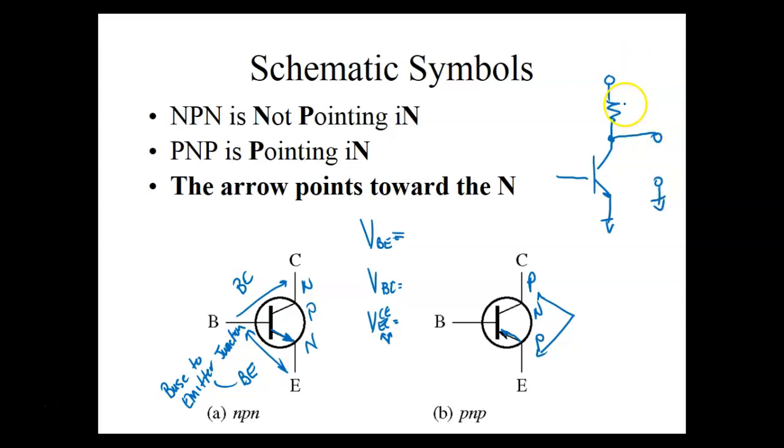Well, if this resistor is dropping 4 volts, and we have 12 volts applied, then voltage collector to emitter would be equal to what? 8 volts. And that would tell me, okay, I got 8 volts on the output. So depending on how you hook your output, you can hook it in series with the transistor, or you can hook it in parallel. So voltage CE would tell us how much the transistor is dropping. So that would be voltage collector to emitter.